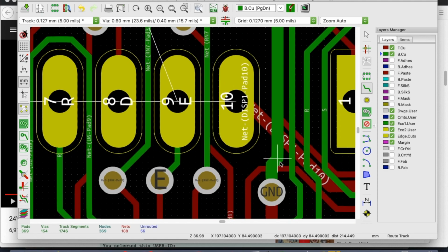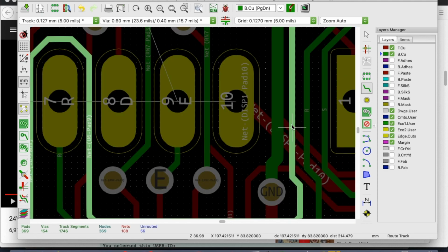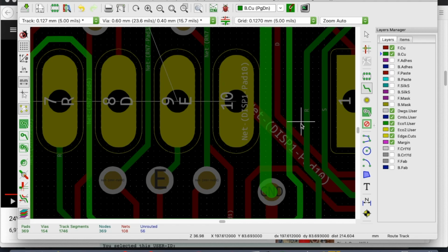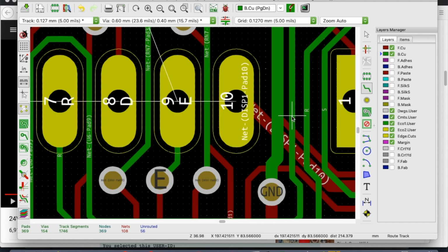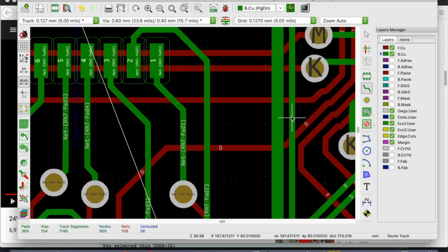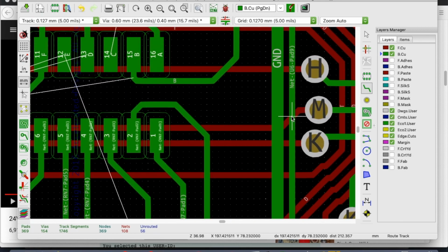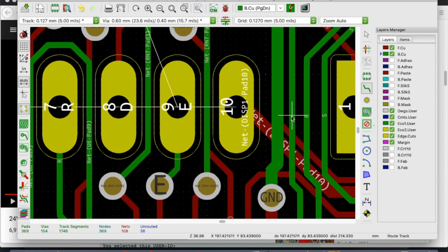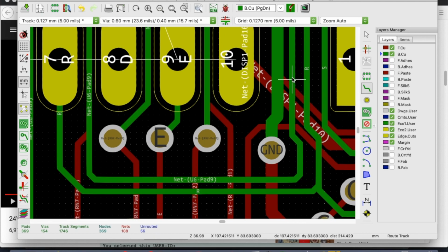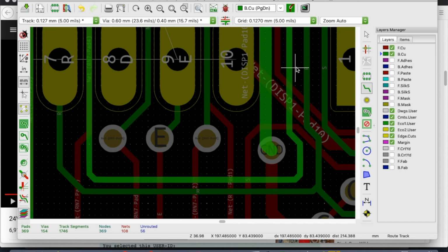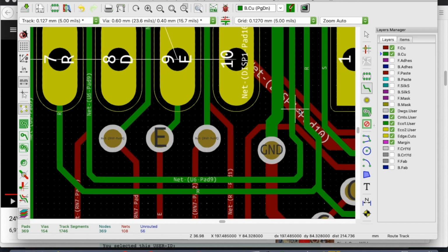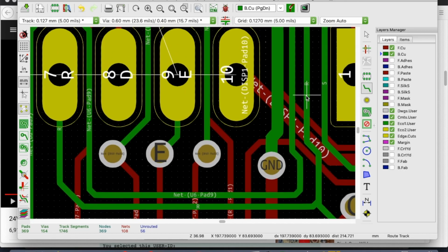Okay, back to our mission at hand. If we drag this one over a little, whoa, something the opposite of what I wanted to have happen. These vias here are blocking this trace from getting moved over. I could put a little kink in it if I need to. But maybe I won't need to.